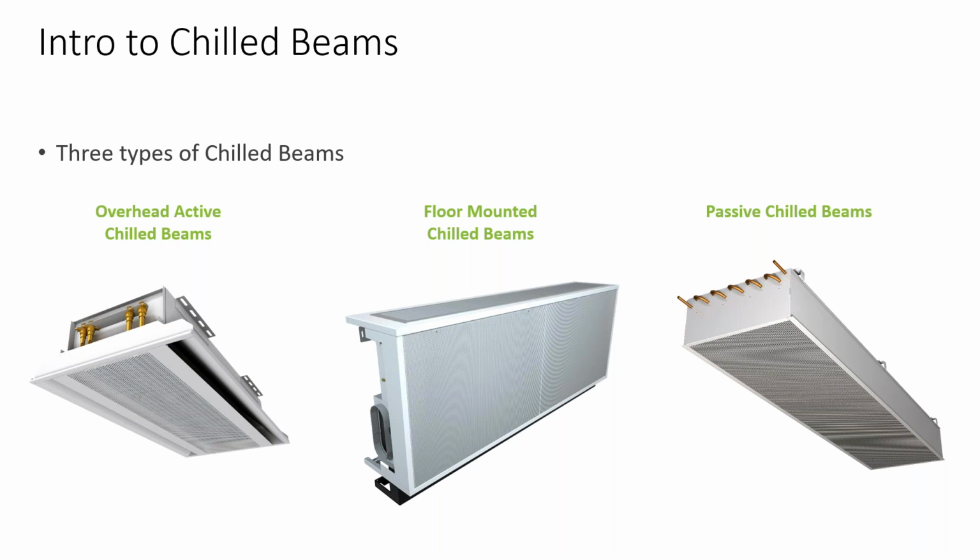And then you have passive beams, which is the initial creation of a chilled beam. It's different from a radiant panel in that it's less of a radiant component and really driven by natural convection, with the warm air getting up behind the coil and cooling off, and then it falls down due to being more dense into the space through that perf face you see.